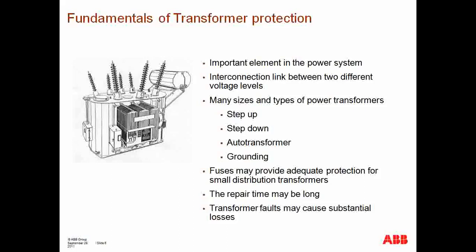The second one would be a step-down transformer, which is the other end of that particular topology, where we now have a transmission system that we would like to connect to a distribution system, which is at a lower voltage level. So then we need a device that will interconnect those two networks and step down the voltage from a particular voltage level to another. An example of that would be a 230 kV to 13.8 transformer, or a 115 kV to 13.8 transformer, and so on.